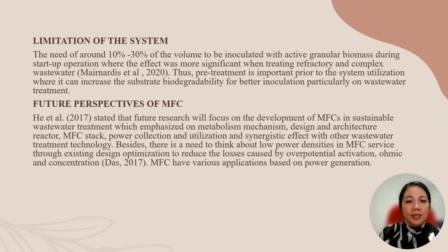He et al. stated that future research will focus on the development of MFC in sustainable wastewater treatment, which emphasizes metabolism mechanism, design and architecture of reactor, MFC stack, power collection and utilization, and synergistic effect with other wastewater treatment technology. Besides, there is a need to address low power densities in MFC through existing design optimization to reduce the losses caused by over-potential, activation, and concentration. MFC has various applications based on power generation.